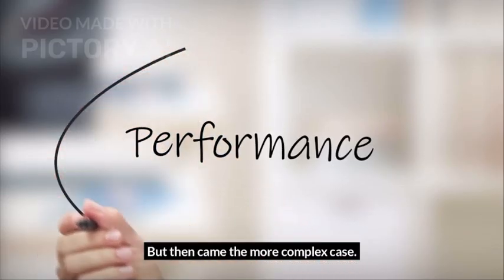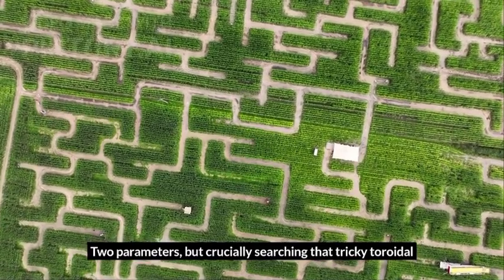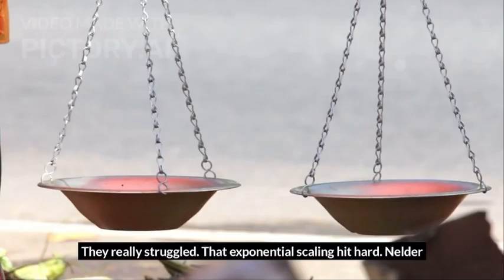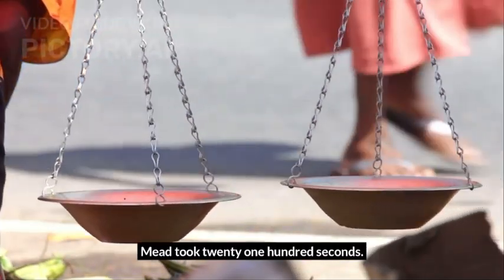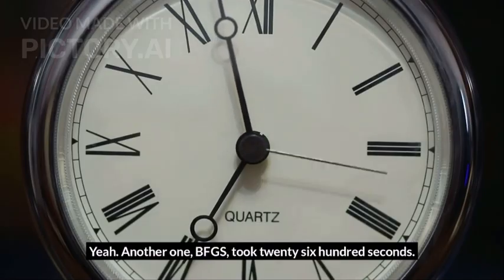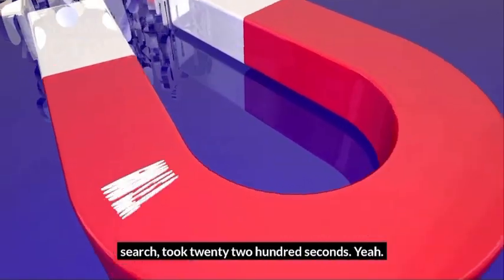But then came the more complex case. Then came case 2, the two-DOF manipulator. 2 parameters, but crucially searching that tricky toroidal configuration space we talked about. And how did classical methods fare here? They really struggled. That exponential scaling hit hard. Nelder-Mead took 2100 seconds. Wow, that's 35 minutes. Yeah. Another one, BFGS, took 2600 seconds. Even particle swarm optimization, which is designed for global search, took 2200 seconds. Basically half an hour or more.